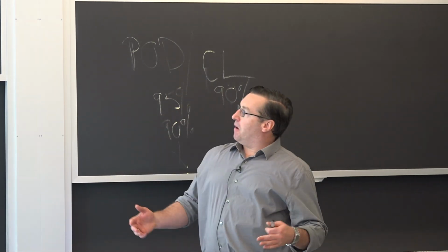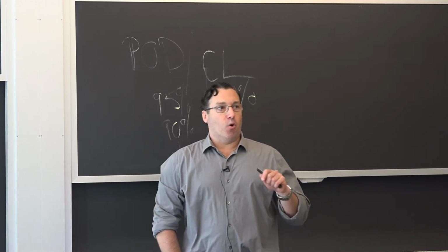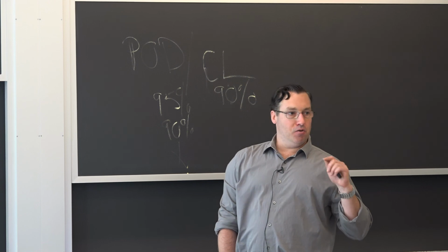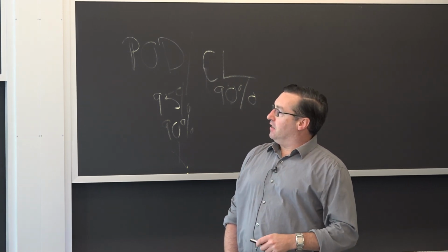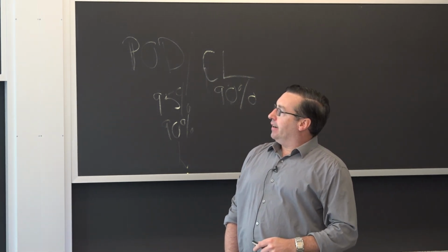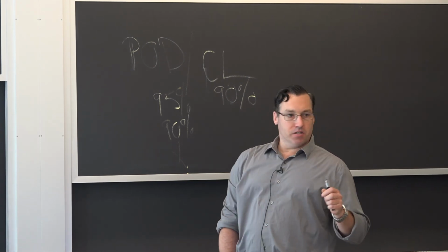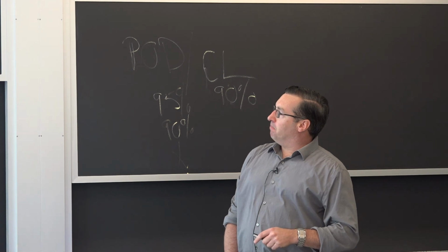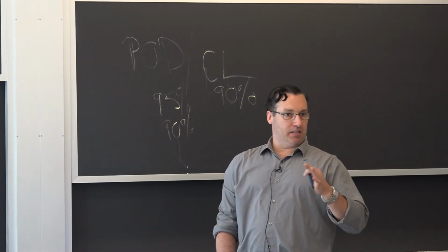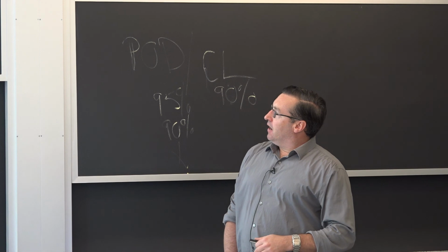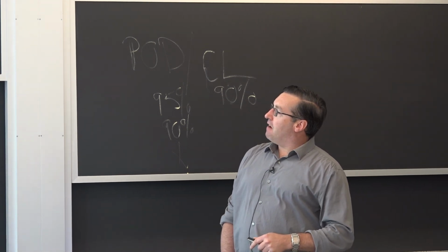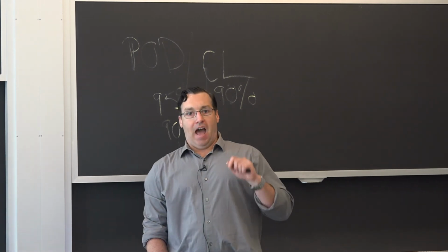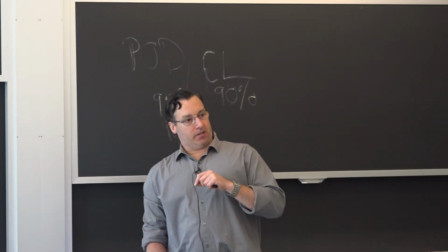Visual inspection, talked about most of this already. Important with visual inspection, the limit of the human eye to detect a flaw is, in general, the rule of thumb about 6 millimeters, depending on what you want to do. Now, you can see smaller flaws than that. It also depends on accessibility at the site, but there's high variability from inspector to inspector. So that's really one of the more limiting factors.